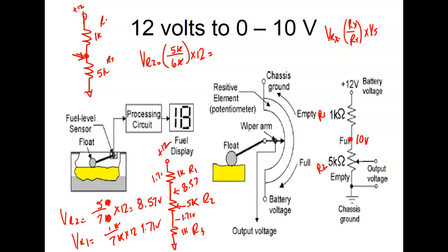So what we've done is we're not using 0 as our bottom number. The bottom would be set by this resistor, the top would be set by this one. So all you have to do is find the voltage drop across this one, or R3, and you don't really need to find the voltage drop across that one.